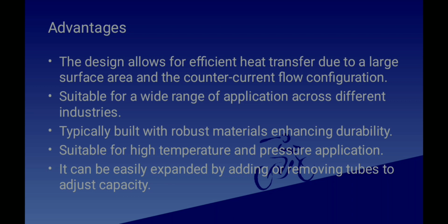And next, it is suitable for high temperature and pressure applications. So due to the build of a shell and tube, it has high durability and withstands high temperature and pressure applications. It can be easily expanded by adding or removing tubes to adjust the capacity. Expanding the heat exchanger is very easy, as we can adjust the capacity by adding or removing tubes in the shell.